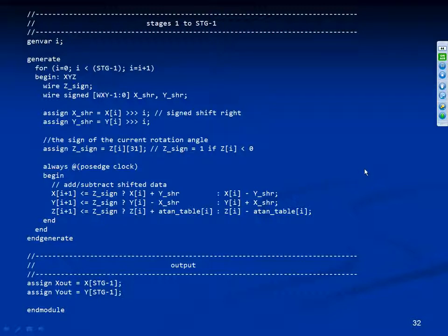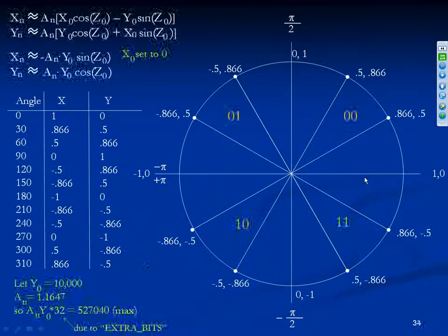If you look in the April 7 release in the receiver.v, you'll see that I have the normal one called CORDIC commented out, and I have this one, CORDIC starting with the letter K, instantiated right now. So you could just comment one out and put the original one back in. It should be real easy to switch between the two to test if you want to try it. You don't have to use this one, but I just want to be able to show it.